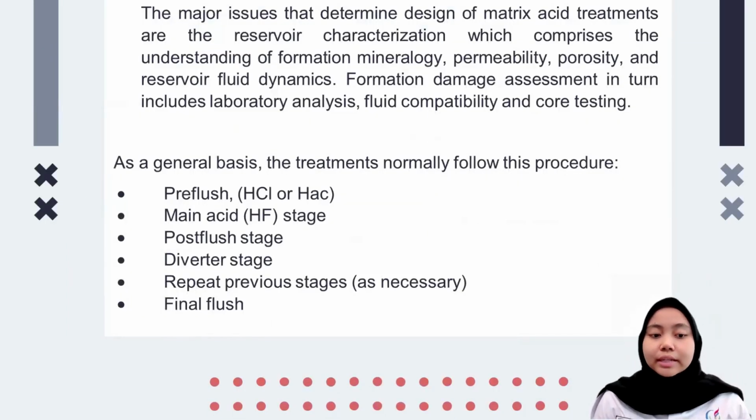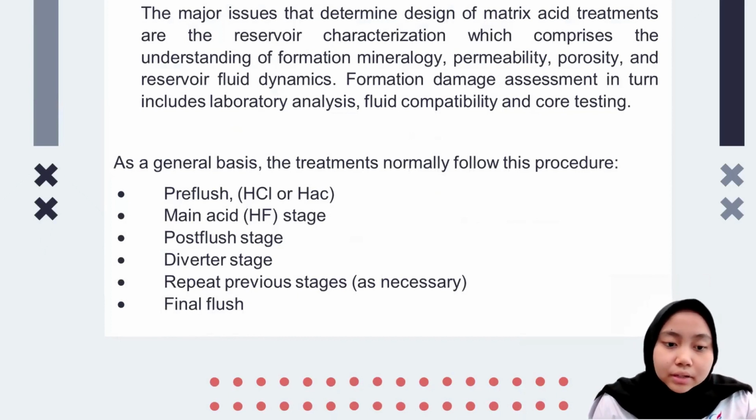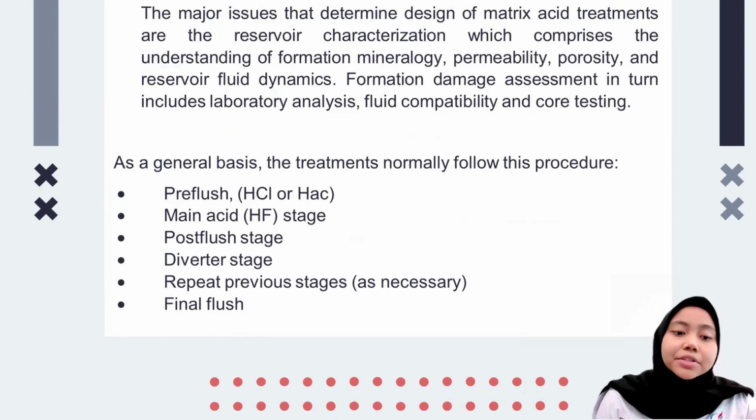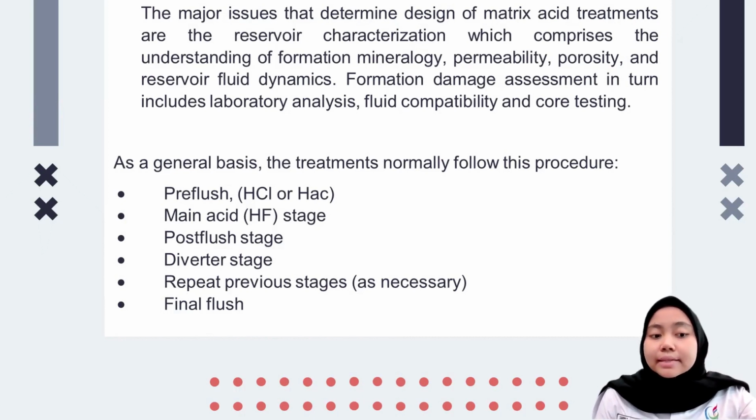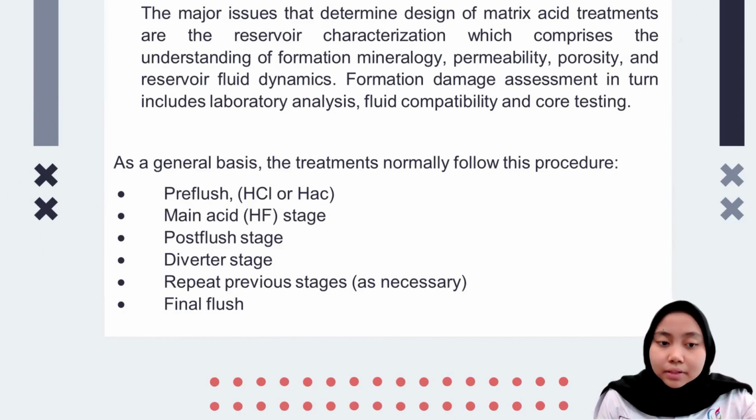The major issues that determine the design of matrix acid treatments are the reservoir characterization, which comprises the understanding of formation mineralogy, permeability, porosity, and reservoir fluid dynamics. Formation damage assessment in turn includes laboratory analysis, fluid compatibility, and core testing. As a general basis, the treatment normally follows this procedure.